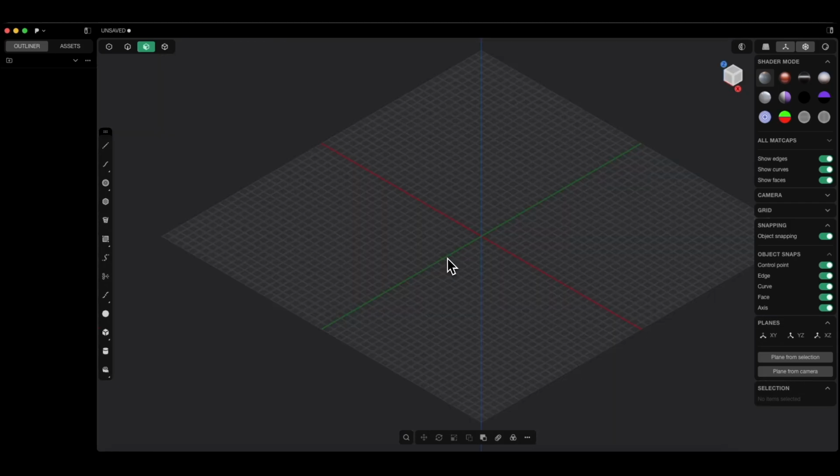Another simple, interesting and useful operation is the radial array. This operation is similar to the rectangular array. A radial array allows you to create additional copies of a solid or selected features of a solid arranged in a circle. In other words, you can create extra copies around a center point.